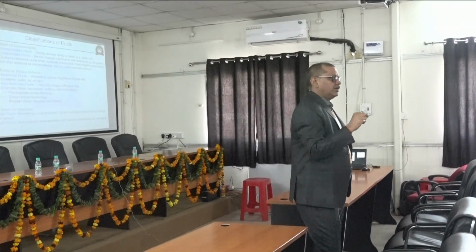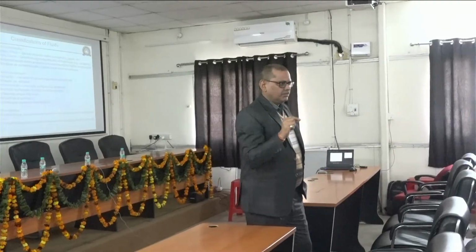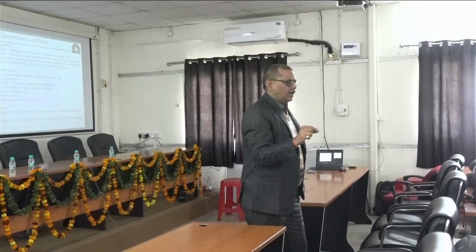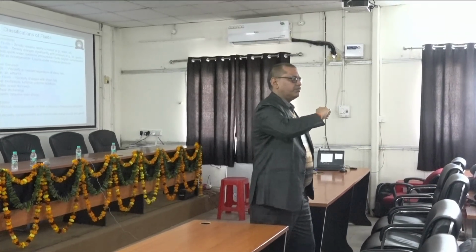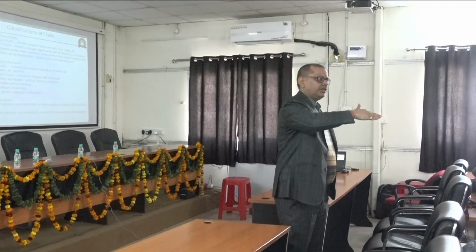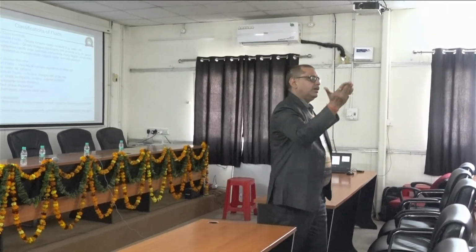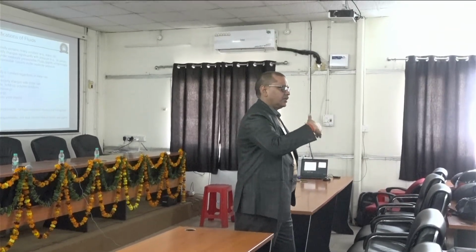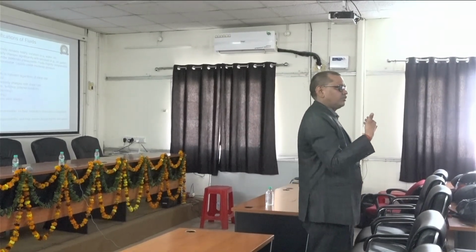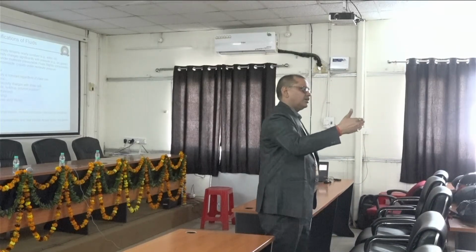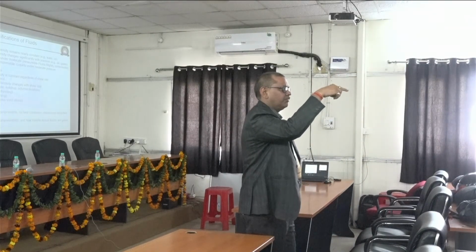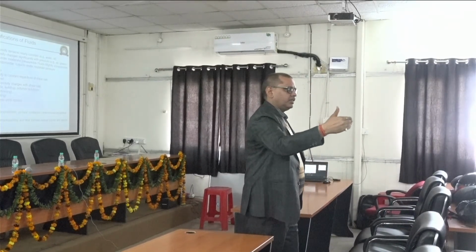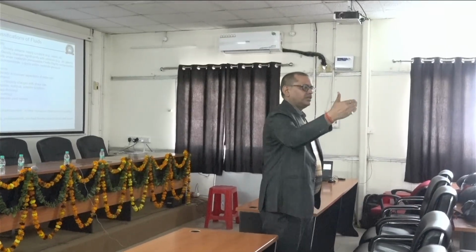So the Bingham plastic model is a linear viscoplastic fluid model. So a viscoplastic fluid model linearly you can define as a Bingham. And again, if the deformation is non-linear, then thickening behavior as well as thinning behavior will be there in addition to the viscous plus plasticity. So what will be the generalized model? You can consider tau is equal to tau 0 plus mu gamma dot to the power n. Here n is the fluid index, which represents the thickening and thinning behavior. Tau 0 represents the plasticity behavior, and mu represents the viscous behavior.